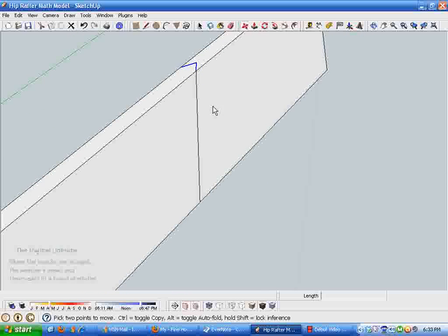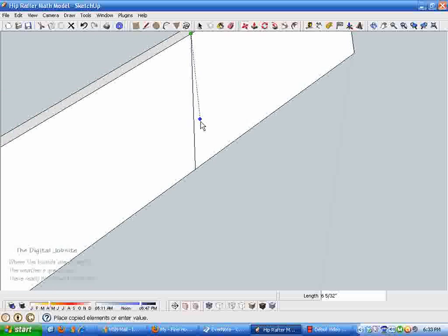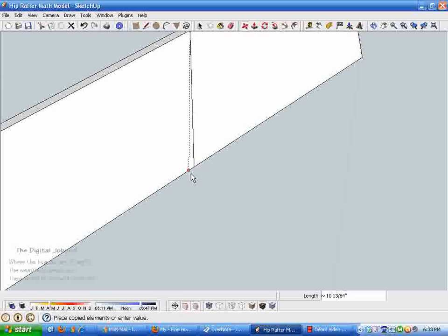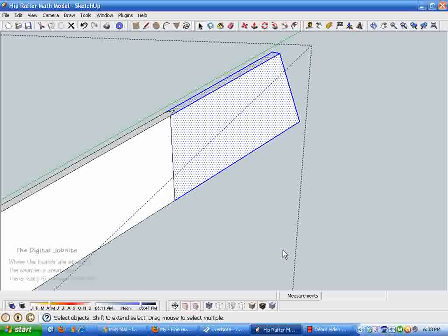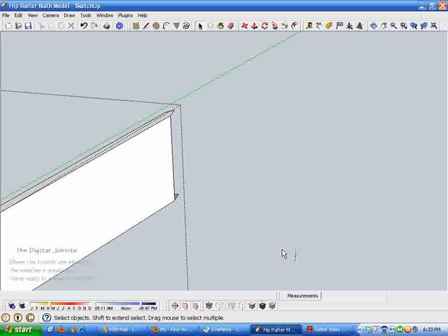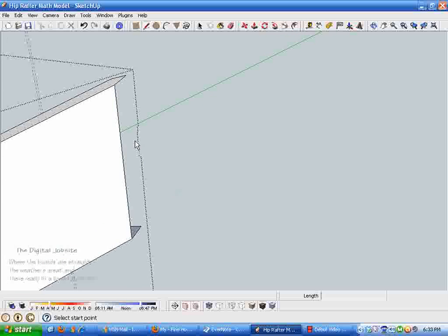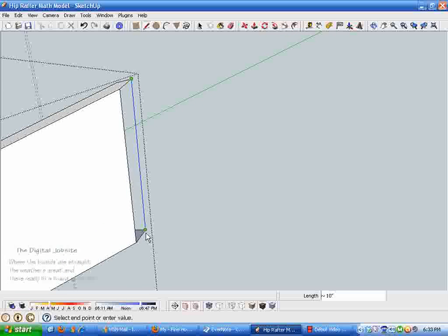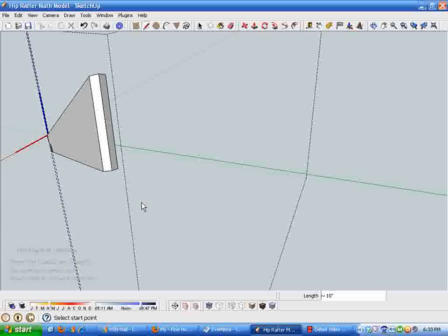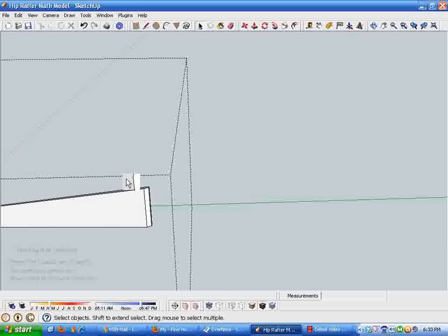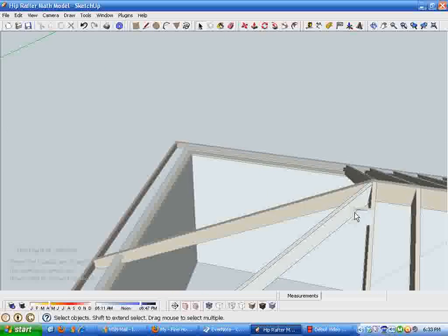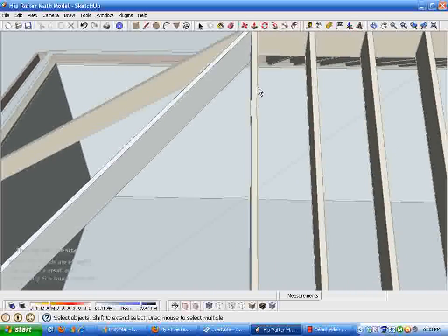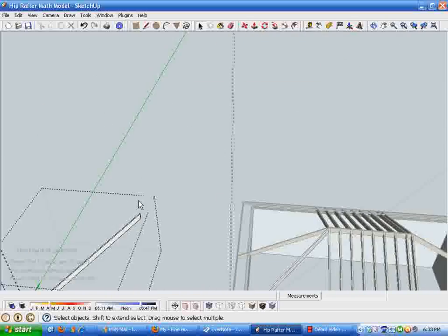Grab the move tool, hit Control, and then you can see I've got those little lines. I'm dragging them straight down till they line up with the end point at the bottom. And now I use right to left, delete the end of that, and then we'll just put our little vertical cut in here, which completes those two faces. Pretty slick way of doing it without drawing every line and without pivoting around here and trying to draw in and around these other framing members.